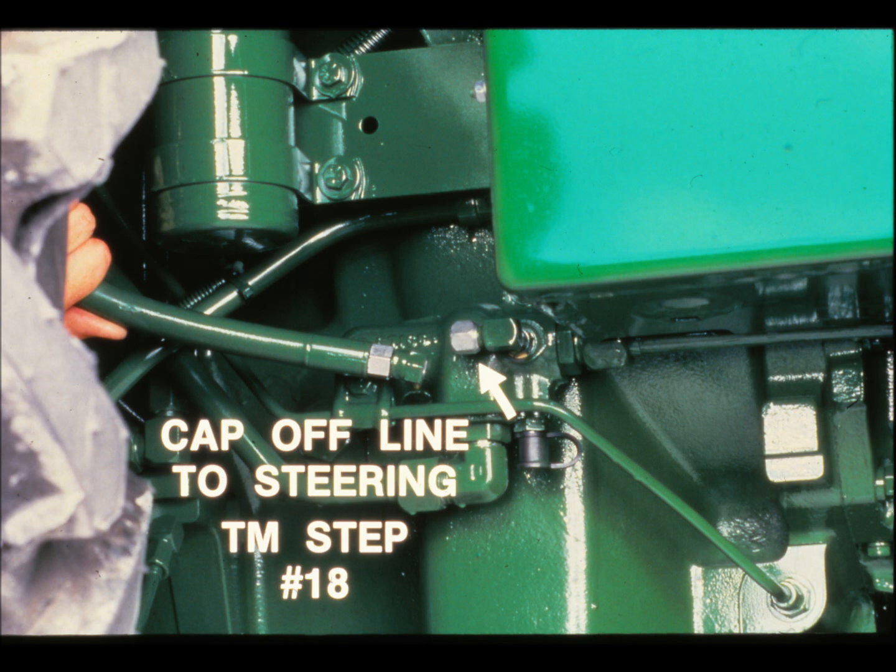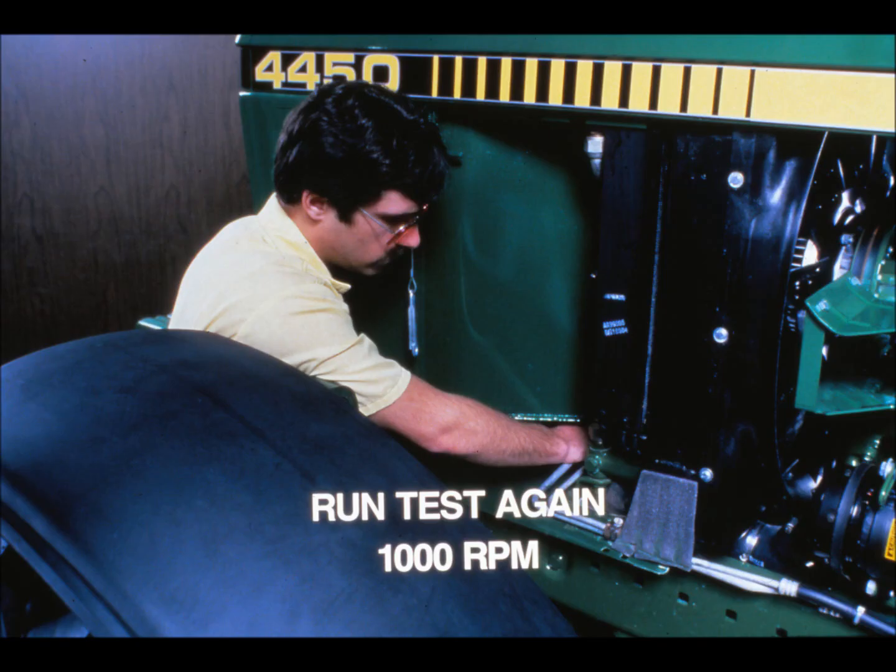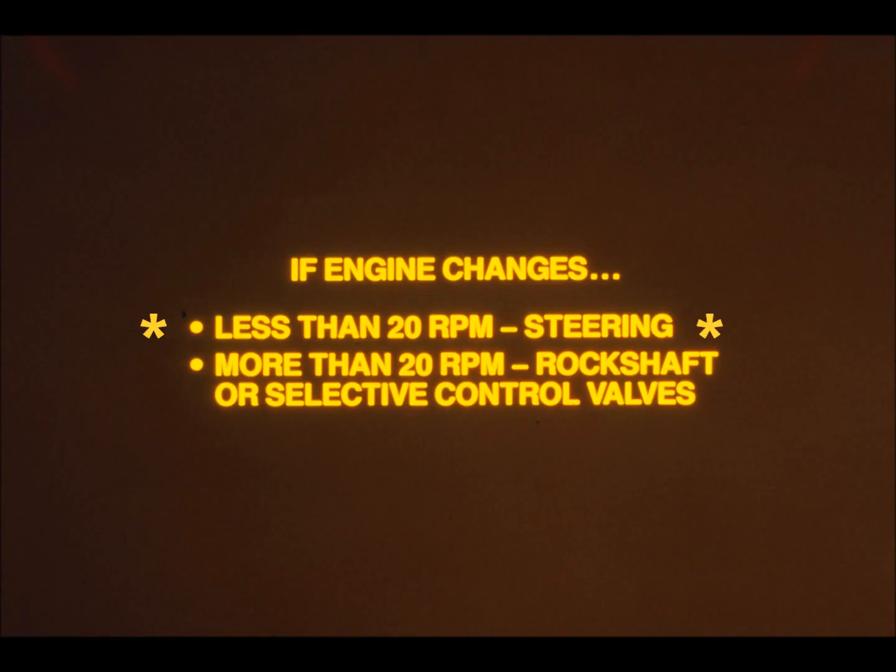Oil flows from the pressure control valve to priority functions like steering and non-priority functions, SCVs and rock shaft. Step 18 isolates the problem by removing the high-pressure line to steering and other priority functions. Put a cap on the PCV elbow. Run the test again. With the engine at 1,000 RPM, record engine speed before and after destroking the main pump. If the engine changes less than 20 RPM, you have isolated the high pressure to return leak. The leak is somewhere in the steering system.